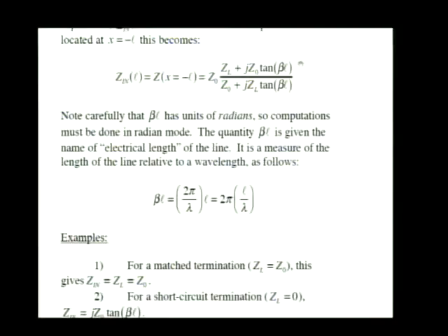For the open circuit, let ZL be something really, really big, and let ZL actually in the limit go to infinity. What that means is that in the numerator, the term here involving ZL completely swamps out the other term. This term can be neglected because ZL is so large. We're actually going to take the limit as ZL goes to infinity. Similarly, in the denominator, this term with the ZL is very, very big compared to that term. Ignore that term and just consider that term.